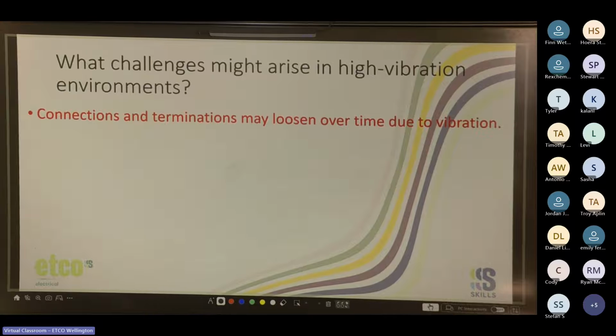So manufacturers' recommendations or requirements that we're supposed to follow are that they're torqued down to a certain specification every 6 months, which obviously for residential isn't practical, but in commercial environments, a lot of guys who do maintenance for commercial buildings have it in their contract that every 6 months they come through and torque down all of the circuit breaker connections.